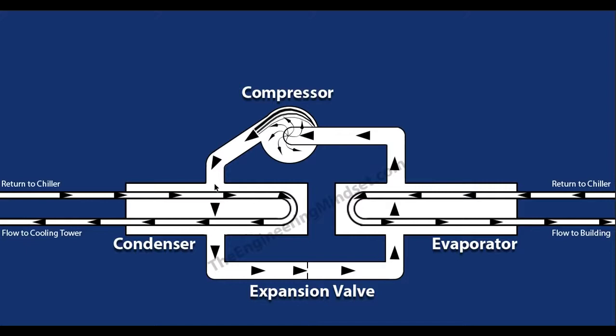The refrigerant comes in and condenses along the tube wall. It does not enter into the water, and the water does not leave. It just condenses on there and continues flowing through there, pushed by the static pressure until it hits the expansion valve. The expansion valve is just expanding that refrigerant, giving it a greater ability to pick up heat when it gets into the evaporator there. So these are the four main components and the three main circuits you need to know about. They will appear in every chiller, of all types, sizes and shapes.